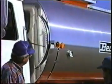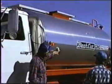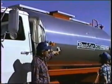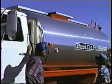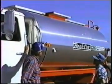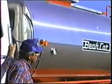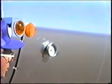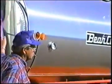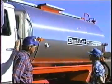Going on back on the tank just a little is a temperature gauge, and that's the temperature of the product in the tank. That gauge really is only accurate if you're circulating the tank well when you read that. Anytime you're heating, of course, you're going to be circulating, and if you are circulating, then the tank gauge is pretty accurate. You'll notice some discrepancies in it when you move the truck around, and that's just because of cool and hot material moving past it.